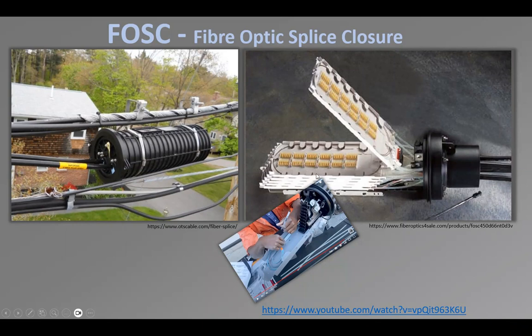Remember, somebody asked me yesterday, do the fiber optics have to be run all the time in a straight line? Can we bend them? Yes, we can. Of course, there's a certain amount of bend that we can apply, but look, this is good, and this is single mode. And if this was multi-mode, you could also bend it that much. How far can you bend those? Well, it depends on the specifications of the cable, of the strength.